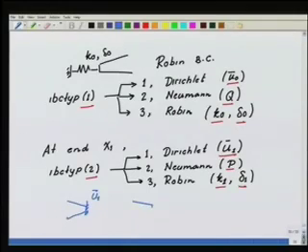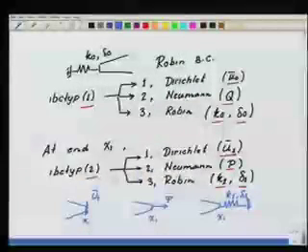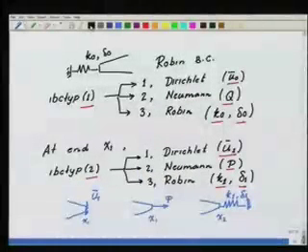When it is 2, I am specifying the end load P. When it is 3, I am specifying the spring constant and the initial compression delta 1 at the end x1. So as far as the boundary condition is concerned, this is the information we would like to have: the boundary condition type and the corresponding data.